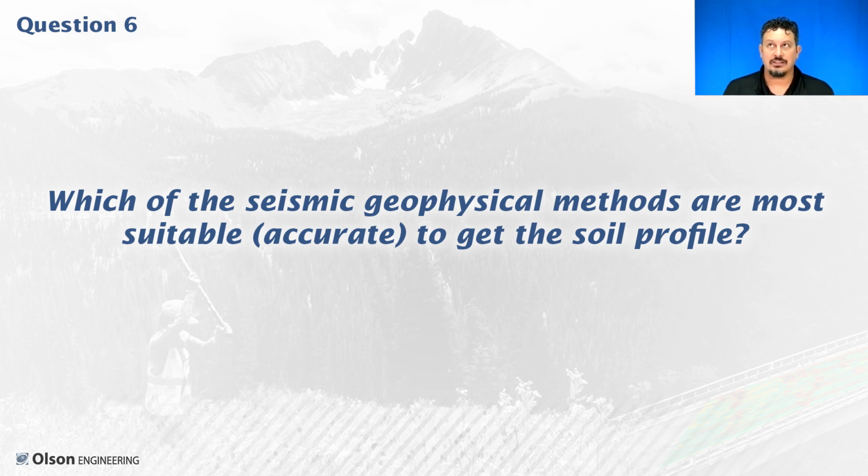If boreholes don't exist, then we have to figure out which method we're going to use. So when I've written proposals to do this in the past, I almost always start with a surface method and put a big caveat that there are sites where the velocity distribution of the subsurface and essentially the attenuation make it impossible to get good data down to 100 feet.